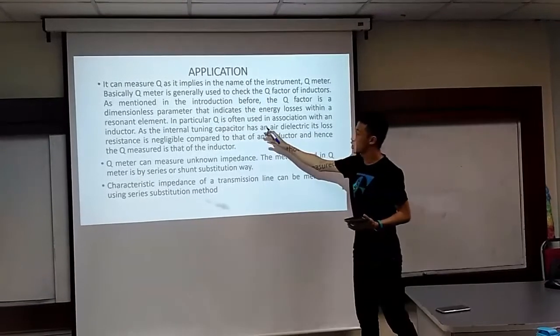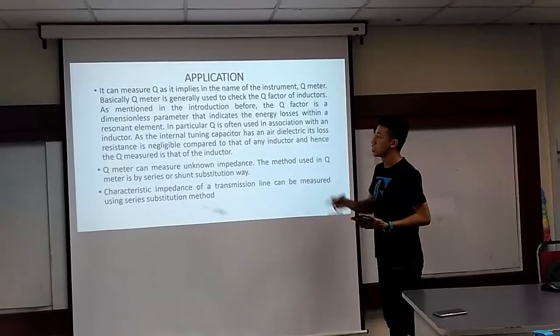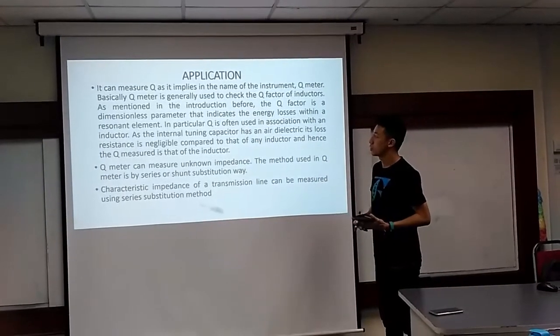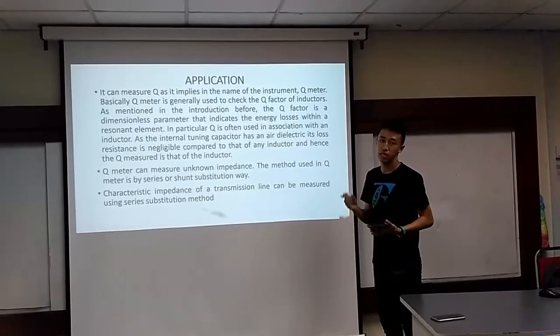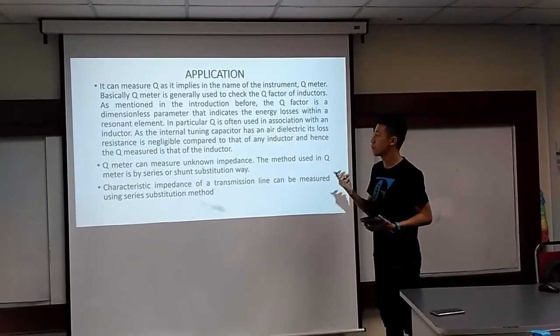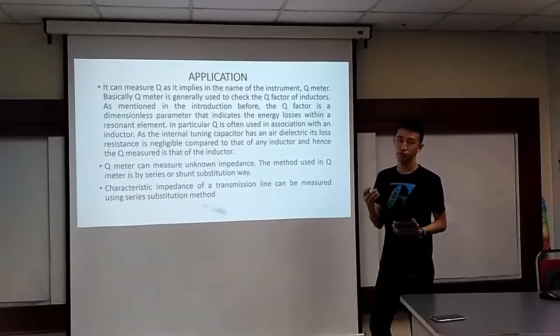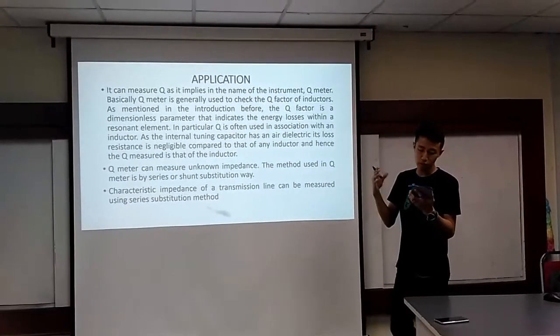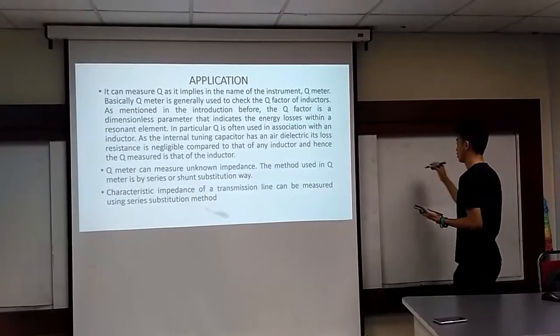In particular, Q is often used in association with an inductor. As the internal tuning capacitor has an air dielectric, its losses are negligible compared to those of any inductor, and hence the Q measured is that of the inductor. So basically, I will proceed with the formula of the quality factor. Okay, as you can see,